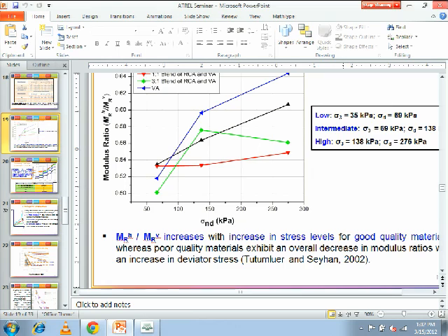And several studies have found that in the field, permanent deformation actually accumulates a lot when you have RAP. But if you just test in the lab for modulus, you actually get a very good indication that it's a very strong material. So it's probably the, I don't want to term it wrong, but viscoelastic or some kind of behavior of the asphalt coating and stuff like that. So it has some type of creep effect over time? Yes, for deformation.